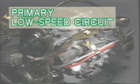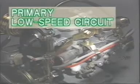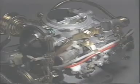The primary low-speed circuit supplies the air-fuel mixture when the vehicle is idling or traveling at low speeds. Here we will use a model to demonstrate. As you can see, the throttle valve opening is very small when the vehicle is idling or traveling at low speed. The amount of air allowed in by the venturi is small, which provides insufficient vacuum to draw up much fuel.